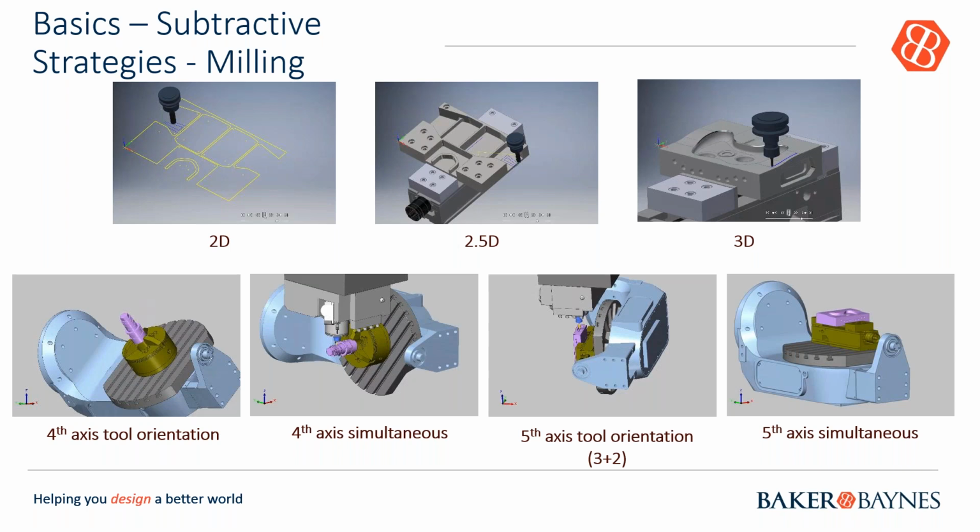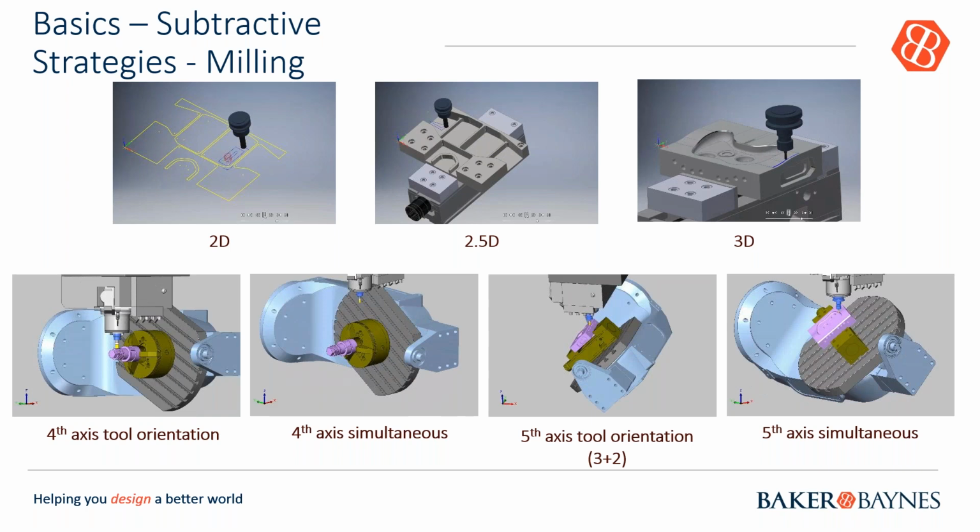And then we've also got the HSM Ultimate, that's embedded in the PDM collection, the Product Design and Manufacturing collection. There's 2 to 5 axis available to you, and you've also got 3+2 axis, multi-axis, as well as turning. With Fusion Standard itself, you've got 3 axis available to you, and the Inventor add-in supports 5 axis as well as the SolidWorks add-in, which is really great. It gives you quite a comprehensive tool to actually do your machining.